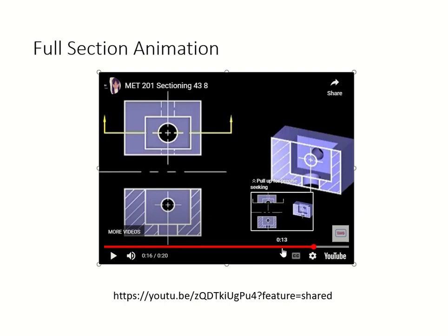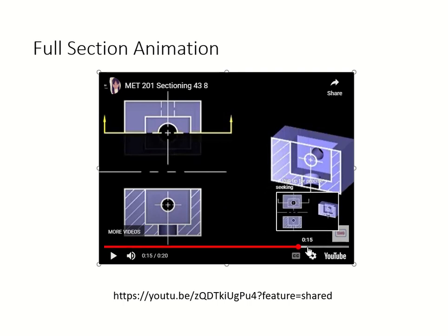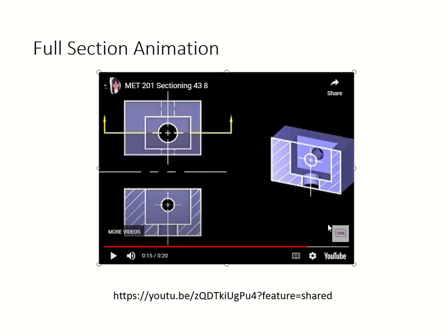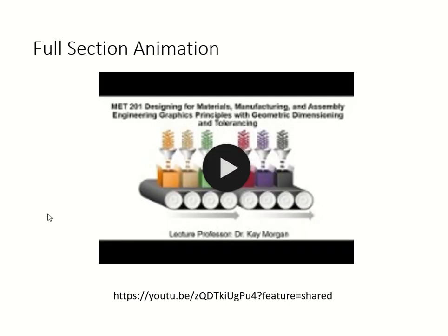Here you can see, pay attention to the top view. After we finish projection, drawing onto the front, we put our removed part back in here. So the completed part is like that. Make sure, because some students forget to put back the removed part. I don't know why. Okay, all right, so that's it for your section view.